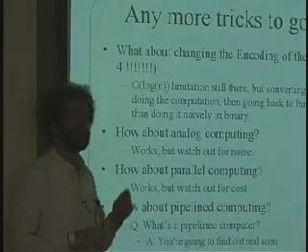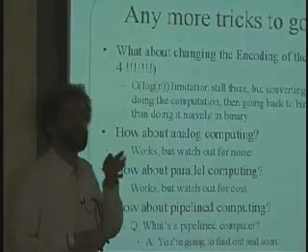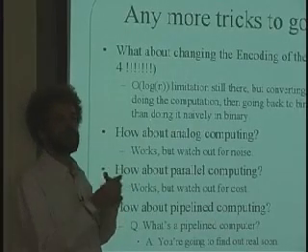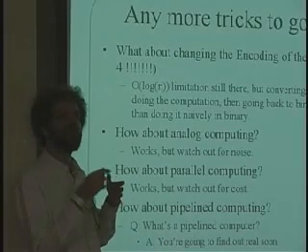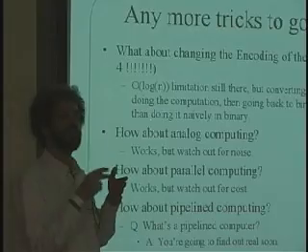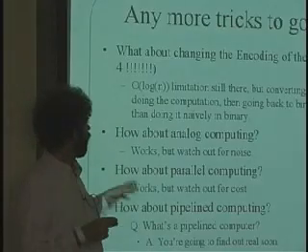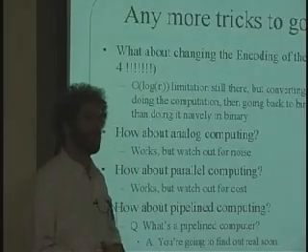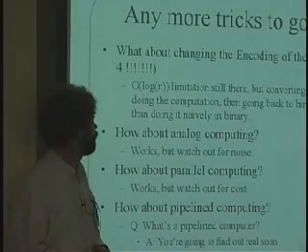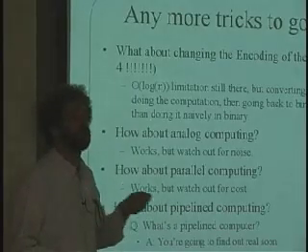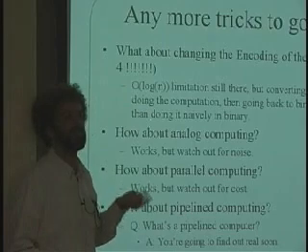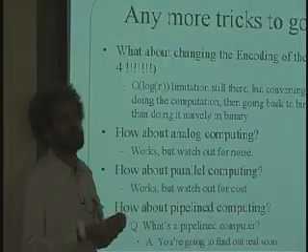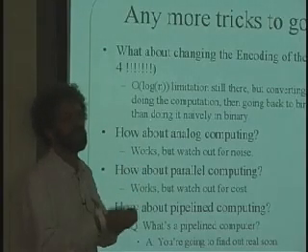It turns out that you could actually encode more possibilities in a voltage range. So you could, for instance, say 0 volts is a 0, 1 volt is a 1, 2 volts is a 2, and 3 volts is a 3. And every wire can now take 2 bits of data, being a number between 0 and 3. And you can do more and more of that to, in the limit, have what's called an analog computer. There you don't have any digital system at all, but you have just a voltage meaning what the number is. And to add 2 voltages to each other, you use an amplifier, what's called a summing amplifier or an op-amp, and you sum the voltages and you get a sum out.